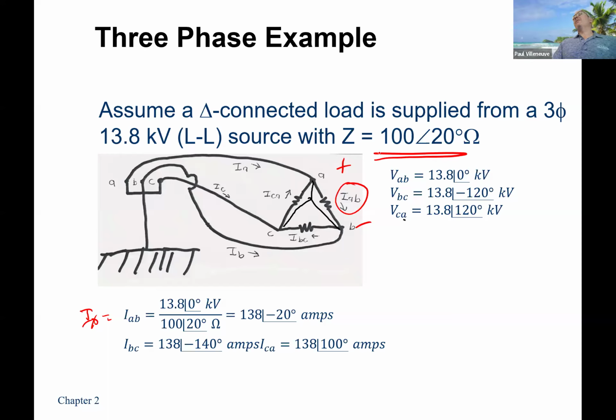There is a three-phase, be very careful of the wording here, resistive load that consists of three resistors that are connected in delta or Y. I said three resistors, not one. So I don't want to ever see an answer that says I've got a 300 ohm three-phase resistor. No, I have three 300 ohm resistors connected in Y or delta to make a resistive load.